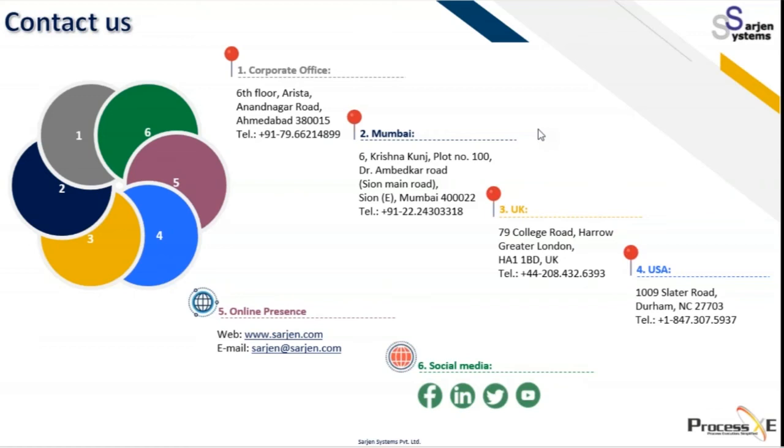So see, if you want to have an EBMR in place, it's very essential to understand the EBMR first. If you want to have the EBMR as a part of your automation, you have an interface with your ERP. The first point, you need to capture all the master data from another system or create it inbuilt in ERP. Second, if you have machines that have the data in your SCADA and PLC, you can create an interface with the machine and capture that data into your manufacturing system. So you can create two kinds of interfaces with your ERP system, with your EBMR system.